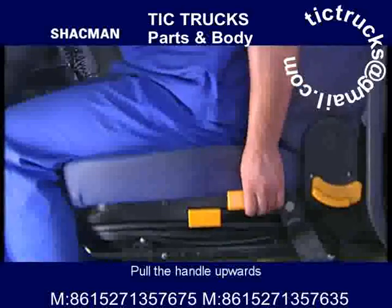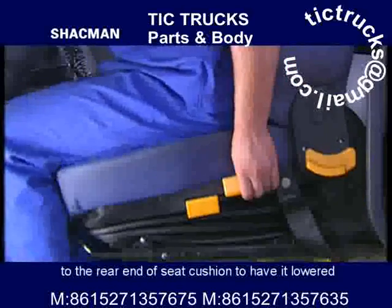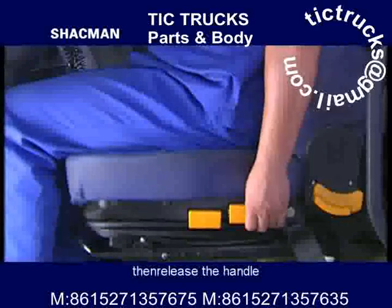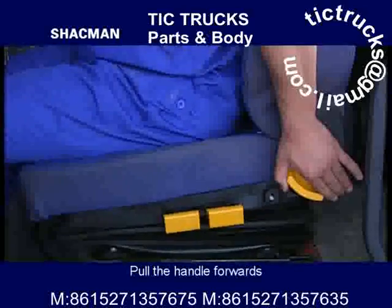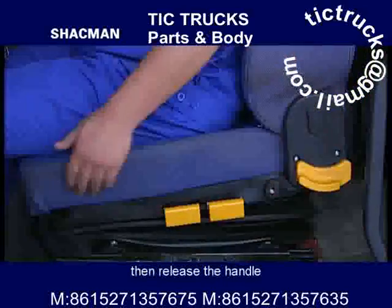Adjustment of rear end height. Pull the handle upwards. Apply an appropriate upward or downward force to the rear end of the seat cushion to have it lowered or lifted to the desired position. Then release the handle. Adjustment of backrest angle. Pull the handle forwards. Turn the backrest to the desired position. Then release the handle.